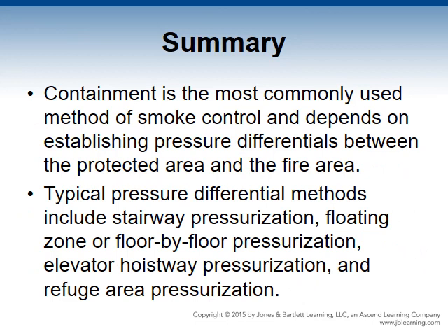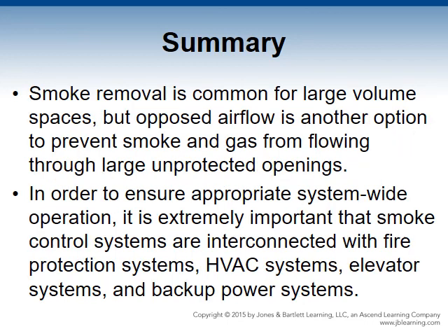Containment is the most commonly used method of smoke control and depends on establishing pressure differences between the protected area and the fire area. Typical pressure differential methods include stairway pressurization, floating zone or floor-by-floor pressurization, elevator hoistway pressurization, and refuge area pressurization as well.